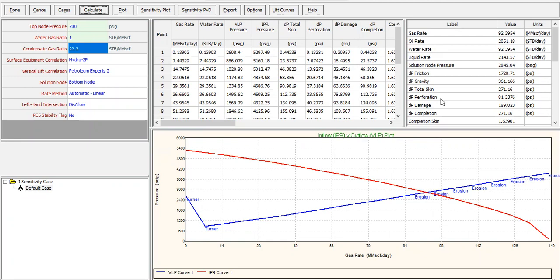Okay, we can get higher operating rate of 92. Do you know why? Because now we assume smaller water gas ratio of 1. Previously, we have 6, which makes the flow heavier. Now the water gas ratio is smaller. That's why we will have operating gas rate higher, 92.